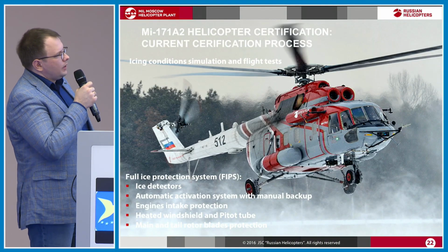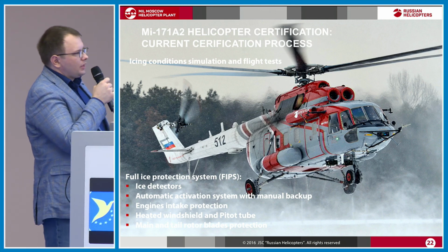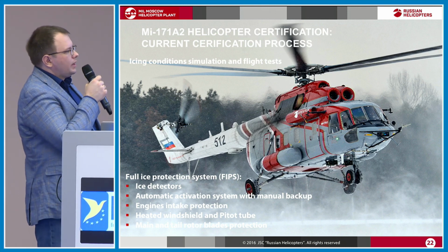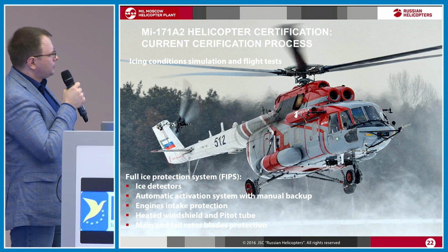So we equipped the helicopter with a full icing protection system, including icing detector, automatic activation system with manual backup, engine intake protection, heated windshields and pitot tubes.